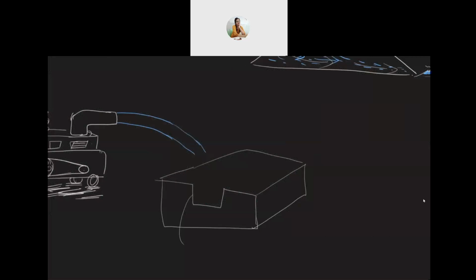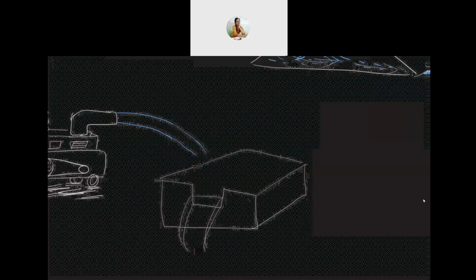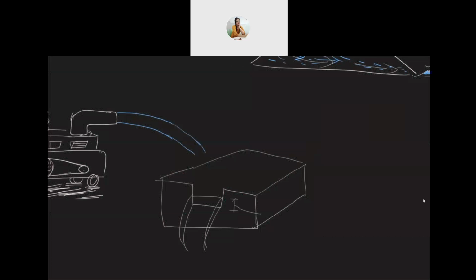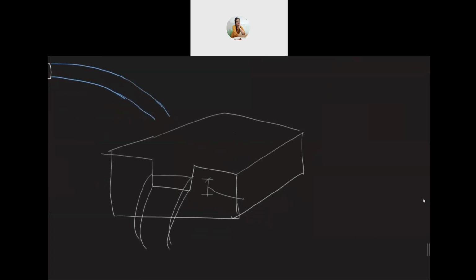So in that notch, instead of measuring the discharge again and again, you simply note down the water level above the notch. Based on that water level, it is very easy to note it down every minute or every half a minute, and that way you can find out the discharge with time.